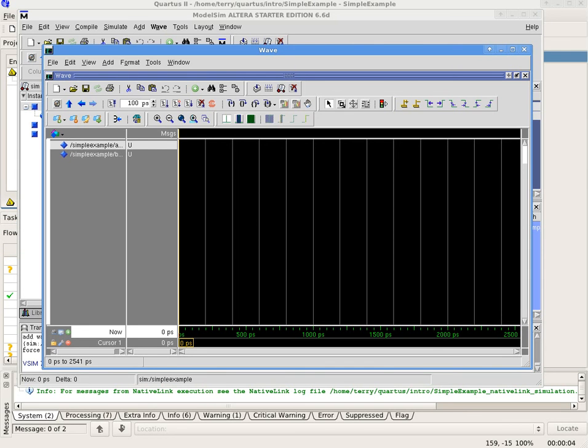In the Tools icons, find the window that contains the period of the signal, for example, 100 nanoseconds. Immediately to the right of that window will be the Run Simulation icon, which looks like a page with a blue down arrow beside it. Select Run Simulation.